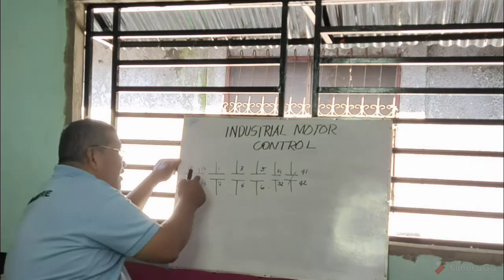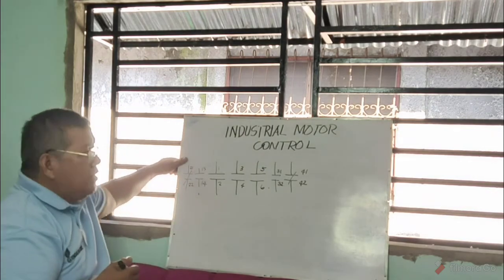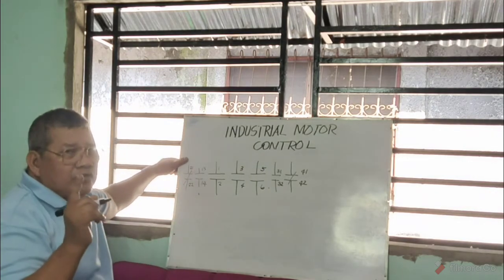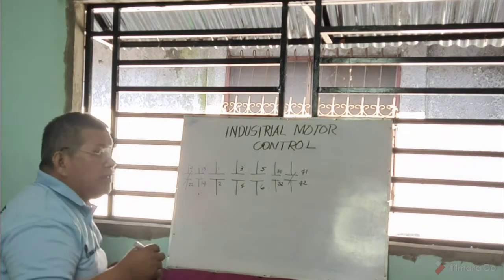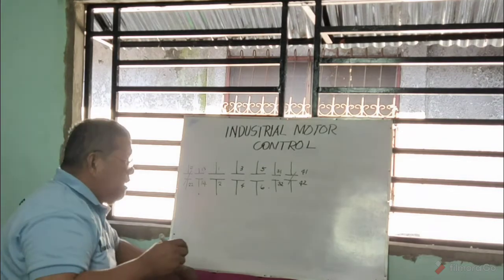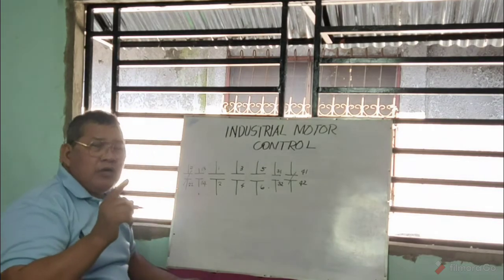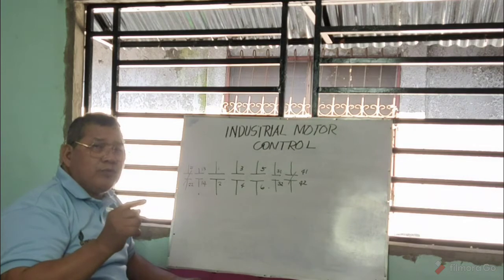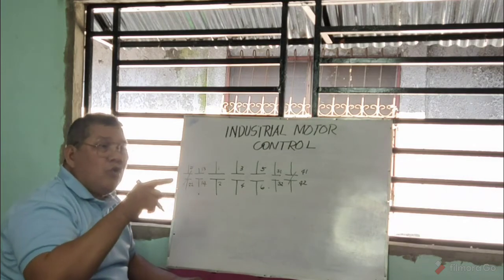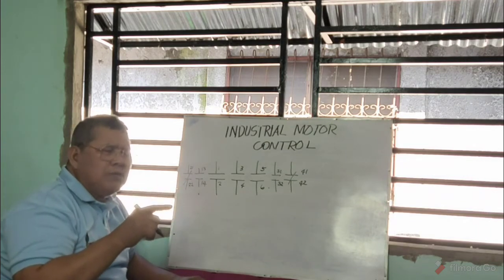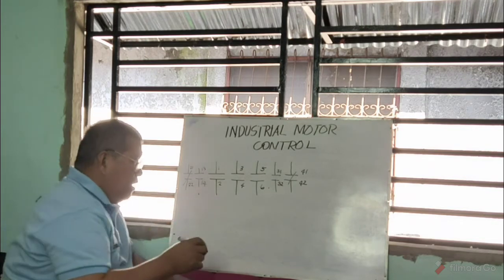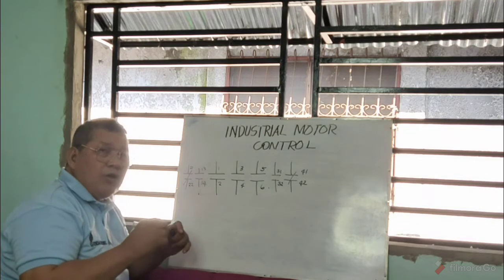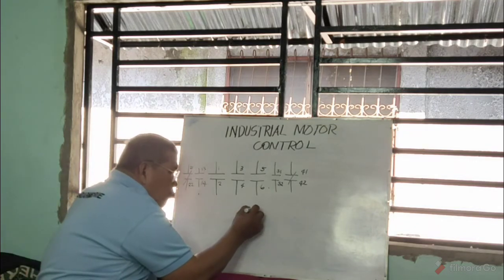So if that is 13, 14, this is the most common, particularly if the contactor is only having one auxiliary contact, then that is normally open. Okay? So those are the symbols. And in the push buttons, because you will be using normally open and normally closed push buttons for on or start, on or off, or sometimes we call it stop and start.